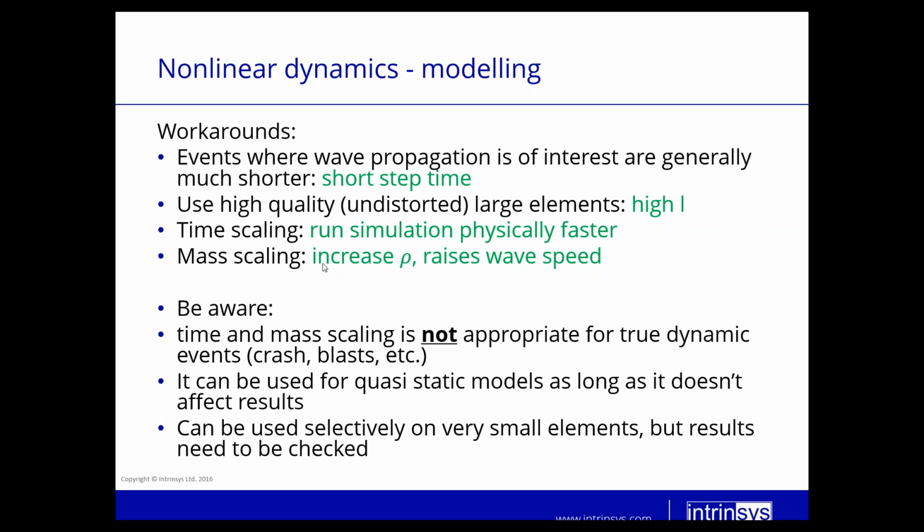Similarly to mass scaling, if you remember the equation we discussed, increasing density would increase the allowable time increment. If you scale up the mass, so scale up the density of your elements, that effectively raises your wave speed.